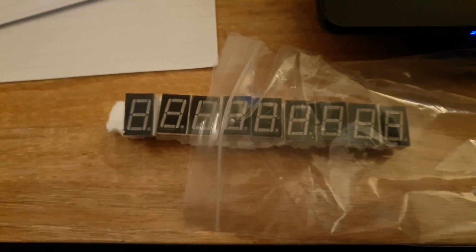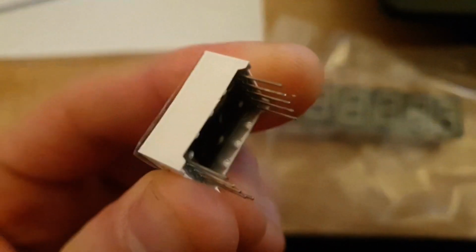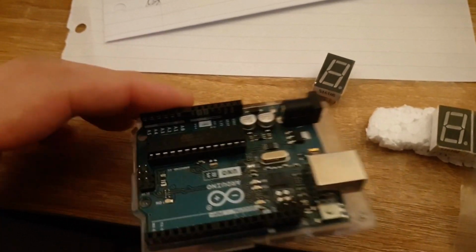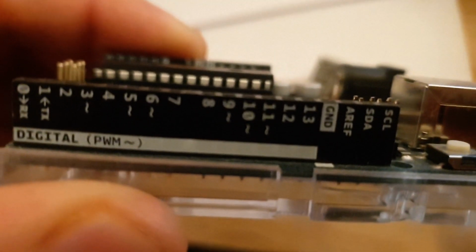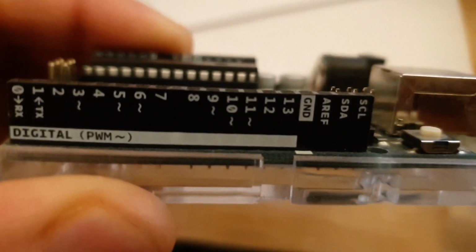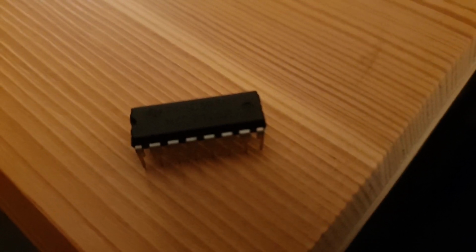I also incorporated a 7-segment display, which has 7 shaped LEDs that are controlled independently. One concern when circuits get more complicated is having enough microcontroller outputs to control all the components. There are 13 outputs on the Arduino, not enough for 2 of these displays. One solution is to use a shift register.